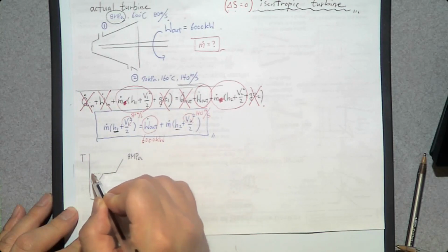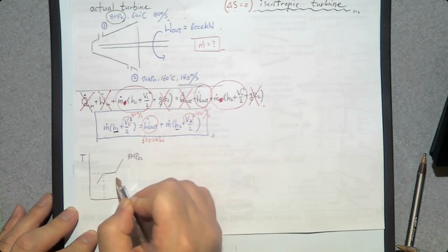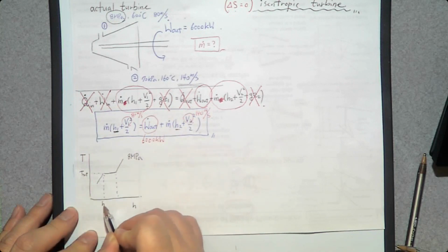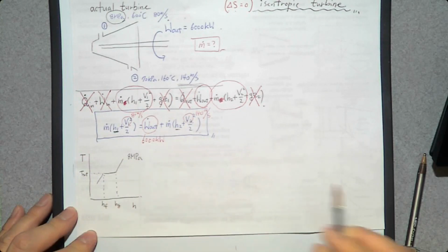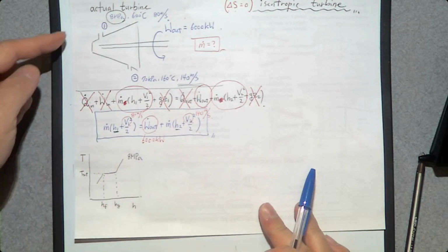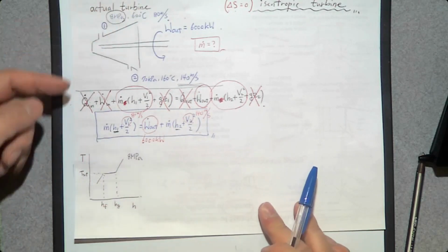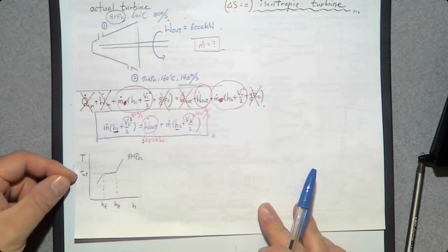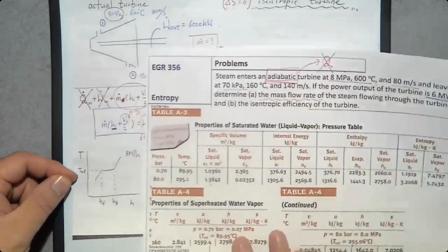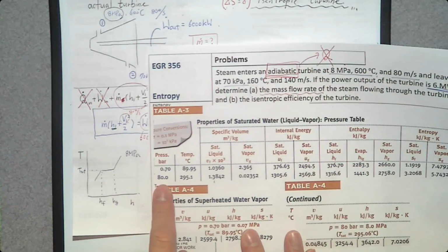And we need to know 3 reference properties. They are T-sat, hf, and hg. By the way, you don't have to find all the values. Since we know the temperature 600 degrees Celsius, if you know the saturation temperature, then we can determine where our system is. So what is the saturation temperature at 8 megapascal?